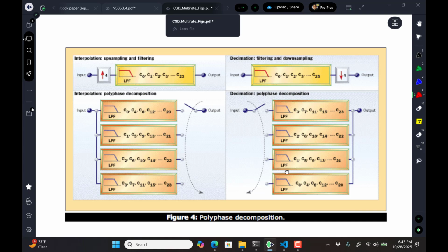And likewise on the downsampler side, as the signal comes in and the commutator in order feeds samples to these various inputs, because now we're going to get a lower output, it just sweeps across here and feeds all the inputs in to drive these subfilters, and then all of those are combined together to form the lower rate output. So the input's coming in faster, it gets distributed across all the subfilters, and then they get combined.